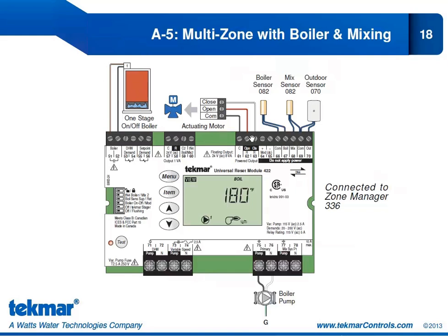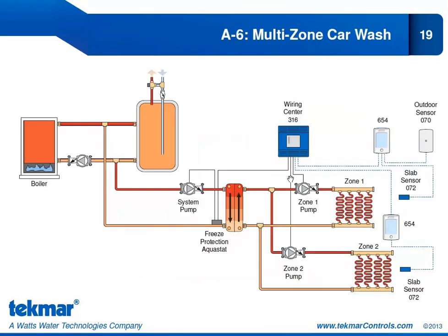It's also operating the mixing device. And because it's operating the boiler and the mixing device, we need the boiler sensor and the mix sensor both to be terminating at the reset module 422. We also have our outdoor sensor 070 connected here as well.